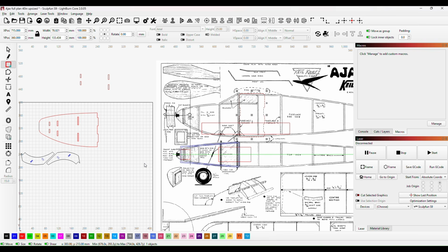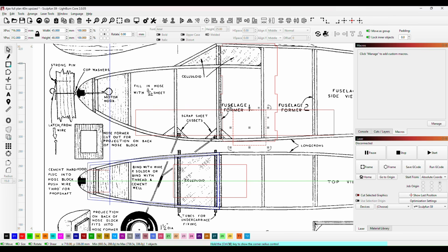The battery itself is 35mm wide, so to give a little bit of clearance either side, if I make a shape 45mm wide, that'll give us plenty of room to get the battery in. So all I'm going to do is bring that across, and I'm going to sit that straight on our former at the height of that line there. So that's set it to the right height.